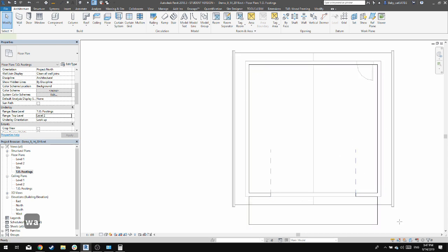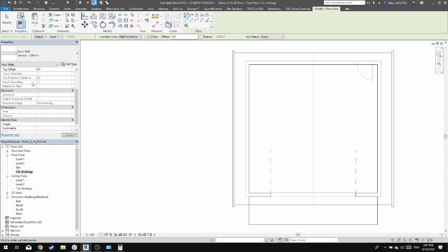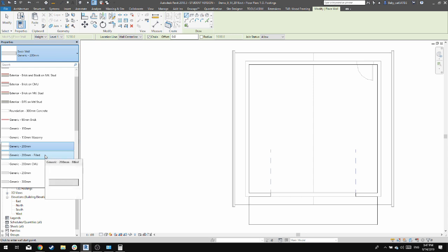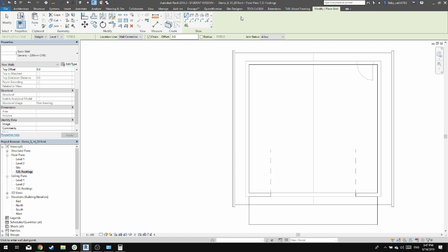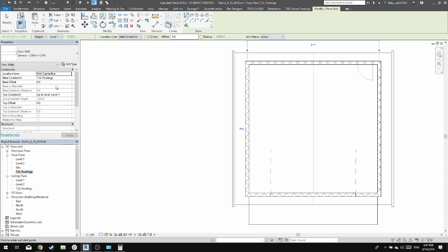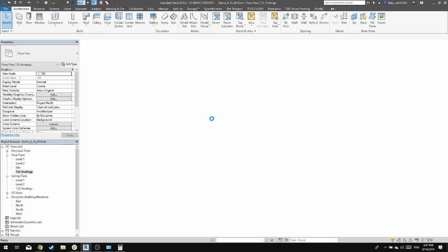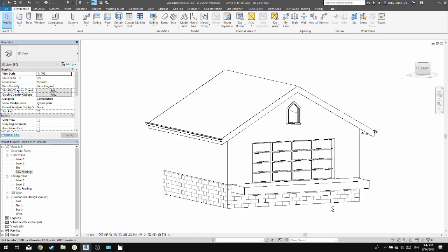where the walls are. So you can open up our wall tool using WA, and we are going to go with generic 200 millimeter CMU concrete masonry units. We can just use the endpoint snapping to draw a new set of walls, and it should automatically be constrained to the right stuff. And then after we're done that, we can go back into the 3D view, make sure that things don't look horrifying.